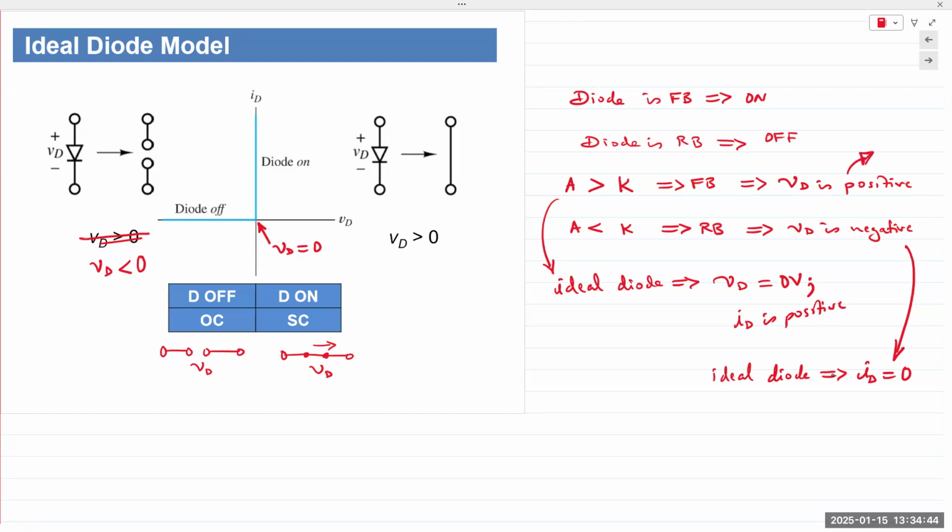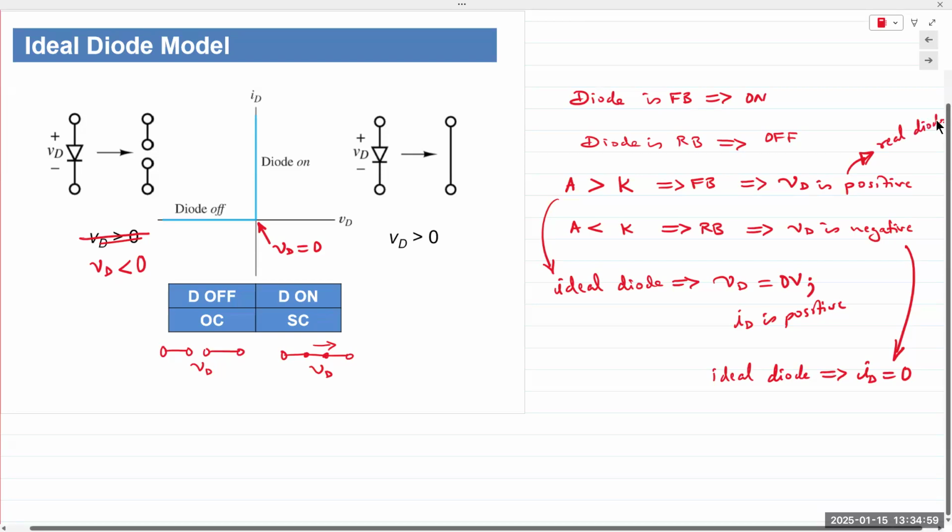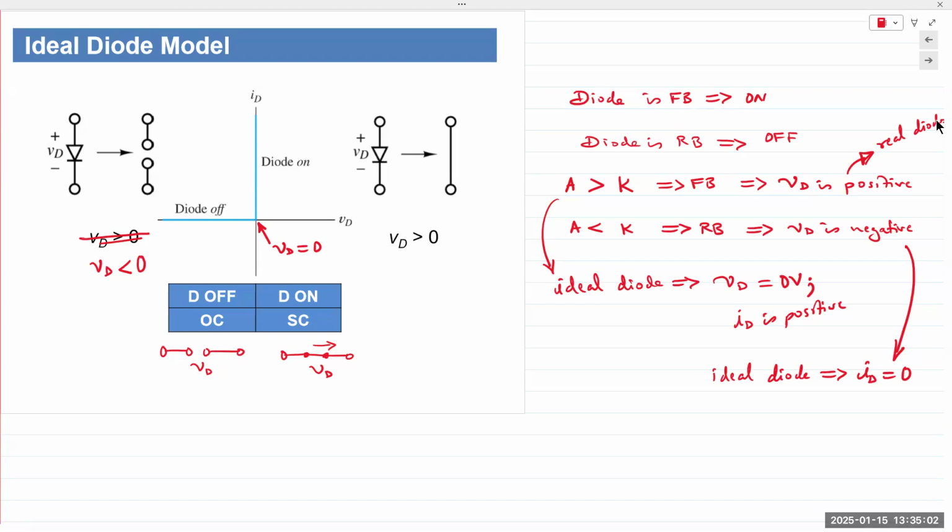So this is in general, meaning non-ideal diodes, real life diodes. If you have a real life diode and you forward bias it, then it must have a positive value for VD. And which leads me to conclude after that, if I'm referring to an ideal diode, then it doesn't require any voltage, VD is equal to 0. The key point is that it should not be negative. If we assume that a diode is forward biased in a real diode or an offset diode model, it must be some positive number. Remember, silicon diodes require 0.6 volts to 0.7 volts to turn on.